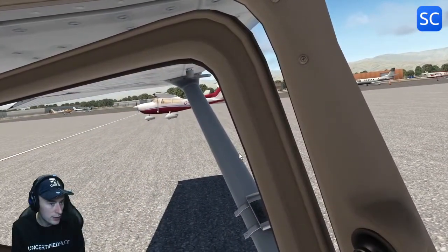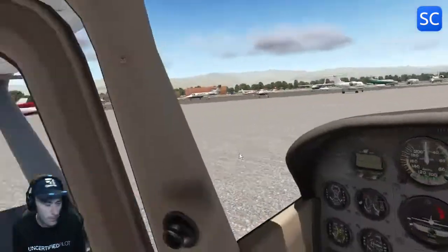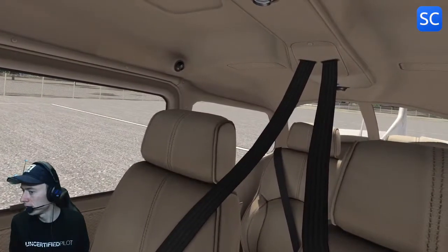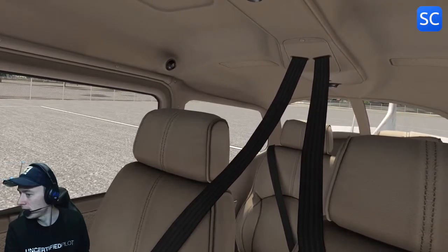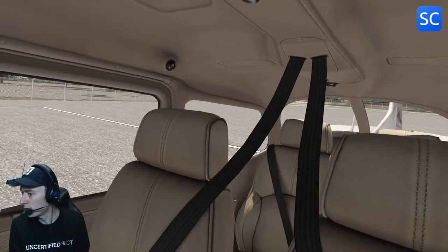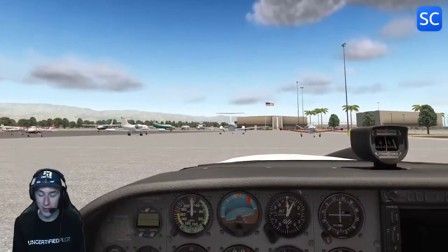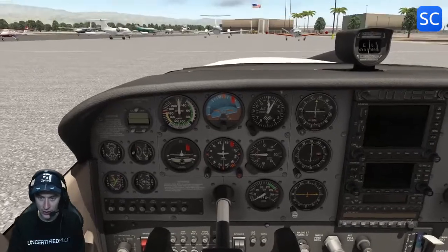Okay, let's also check the control surfaces. Yoke to the right, then that one goes down, that one goes up, down, and up. Makes sense. Elevator. Feels good. And my trim tab, I can see it turn. Yeah, it turns as well. I mean, the trimming wheel can work, but it doesn't mean that the surface is actually changing as well. So it's important to check. And that completes our cold and dark check.